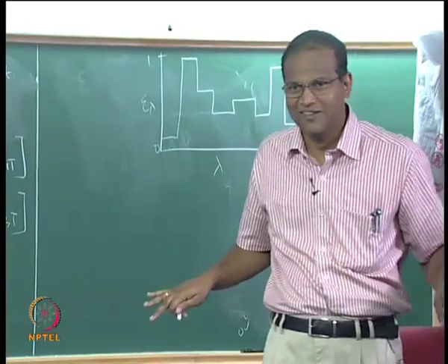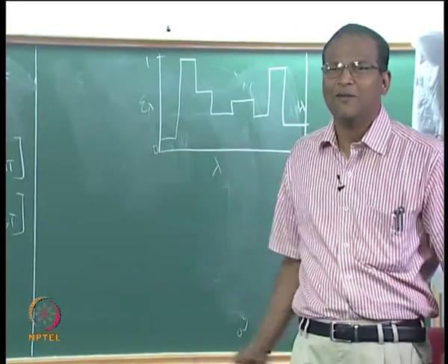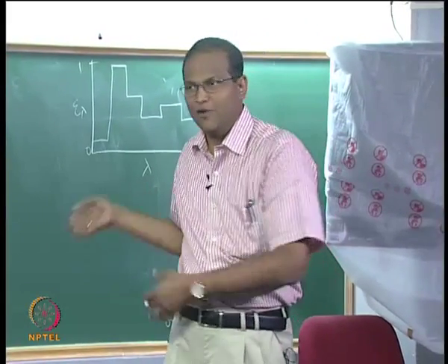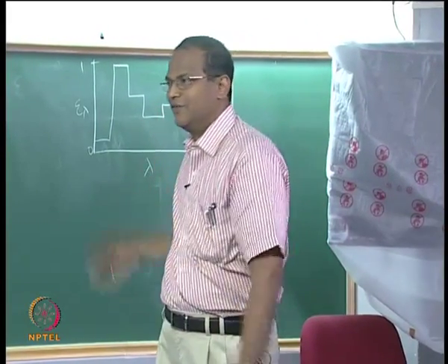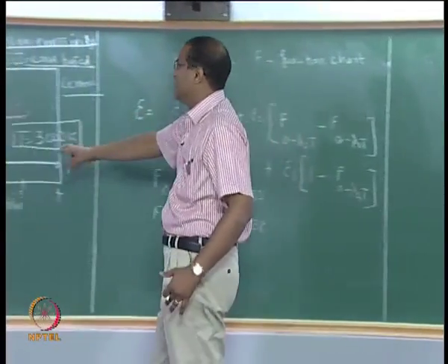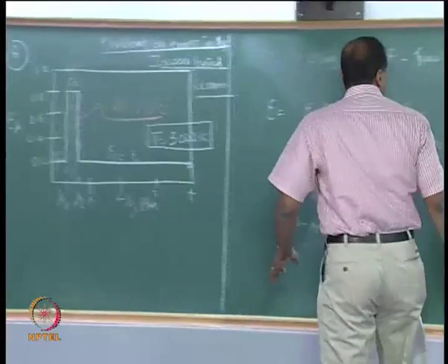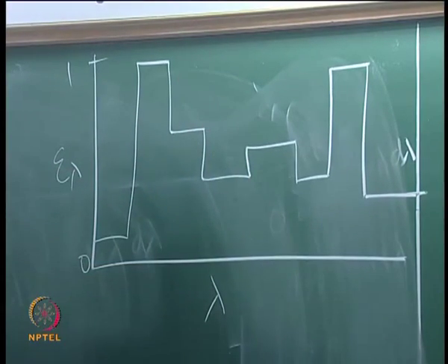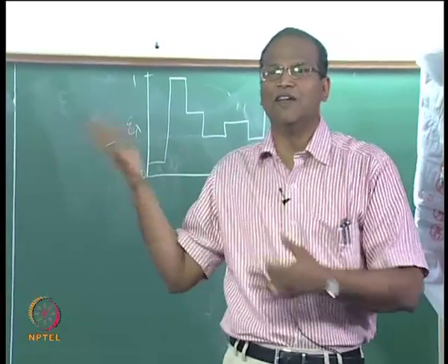So you spent 20 minutes to calculate, but it is pointless. It is just a mathematical quantity we can keep, but I don't think there will be surfaces so fancy like this. Surfaces will be like this, maybe exhibiting some other emissivity in another portion of the spectrum. But if you see radiation heat transfer books, such things are there. This is basically an academic exercise, so that the students get sharper and are very comfortable with the F function chart.